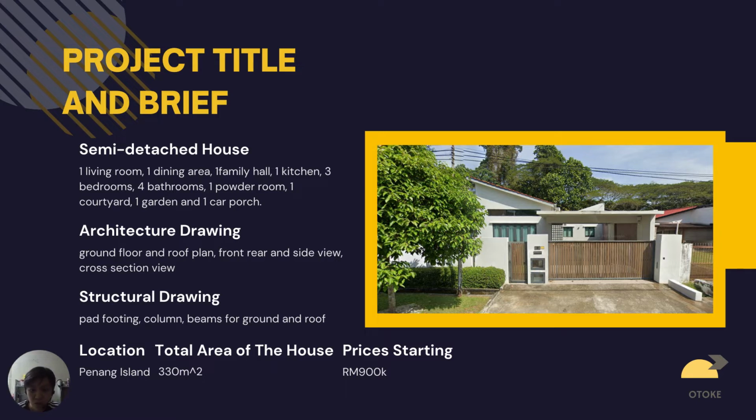Architectural drawing such as ground floor and roof plan, front, rear and side view, and some cross-section view. Each architectural drawing shows the view of the house with detailed dimensions. Structural drawing such as pad footing, ground beam, and roof beam drawing contain the details that we use to build this house, like the size of the pad footing and the size of the beam of ground and roof.